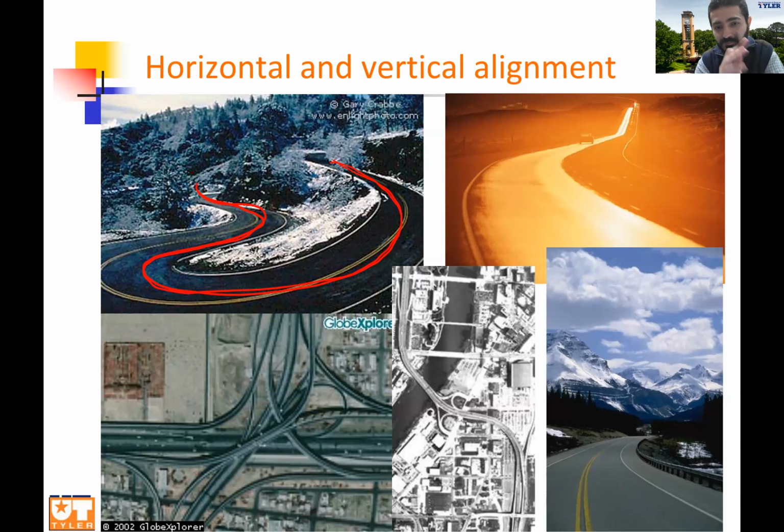I tried them, and I'm pretty sure some of you already did, and that is an art to design such a roadway. If you ever wondered why we do not have much straighter roads, why don't we cut into the mountains? Again, it's very costly. So to solve the problem, we need to study the horizontal and vertical alignment equations to still have cost-efficient roadways, yet safe ones as well. How can I have enough sight distance for those drivers so they can see a danger well in advance, and then react to it at the right time?